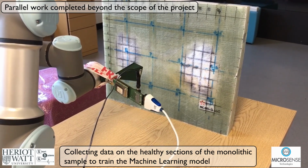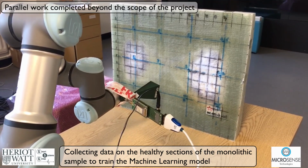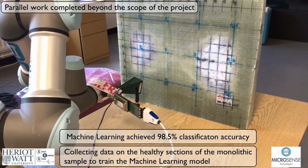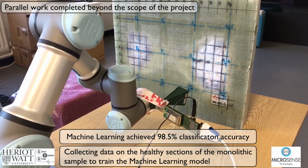The utilisation of machine learning models on FMCW radar return signals collected from the different turbine blade samples demonstrate that we can classify blade types by composition and diameter differentials of 3 mm with 98.5% classification accuracy.